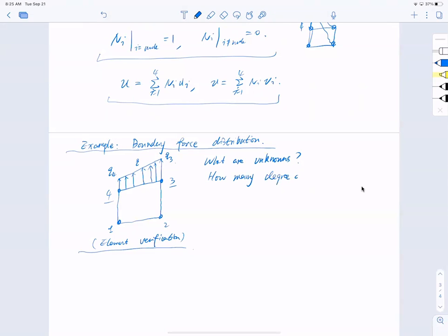For each node, for all of them, we have 8 displacements. When we say degree of freedom, it is usually in terms of position or location in space. If you know the nodal displacement for all 4 nodes, the shape or the position of the element is fixed. The displacement field is also fixed because you have the shape function to interpolate within the element. So that's correct, degree of freedom.